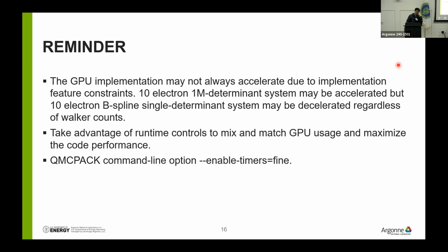So if you have questions about performance, remember that you can always enable the QMCPACK timers. Just set this option and you will get a report at the end of your execution. One more reminder: QMCPACK has features to stop a calculation on the fly. So if you want to do a quick run and you don't know how long it runs, and you figure you have enough statistics and just want to read the timer, you can stop the code on the fly and it will finish by itself, and you can see the time to get another idea.